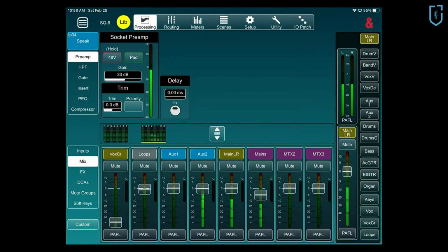it's taking my whole mix, and I can apply EQ just to the room, and it's not affecting my main left right, but I can cut volume to the room, or I could boost volume to the room. So this is the last stage before it leaves the console. That's where I'm applying my cut to sort of get the volume in the room.